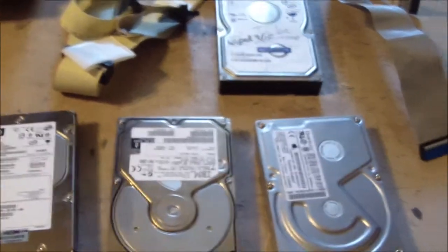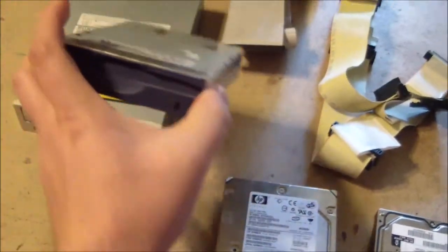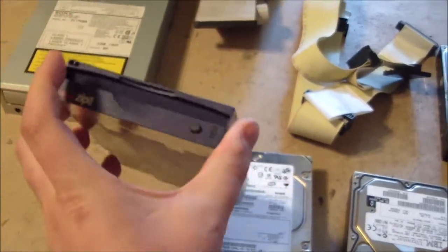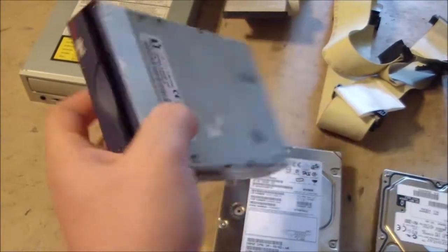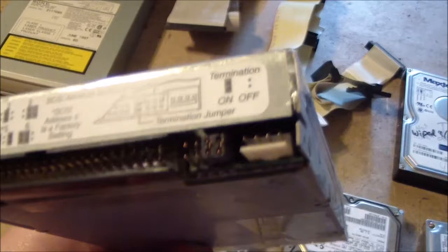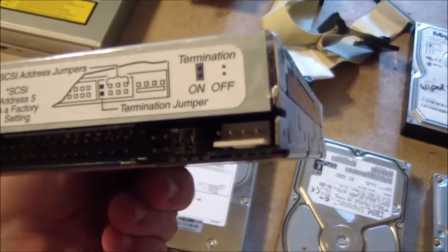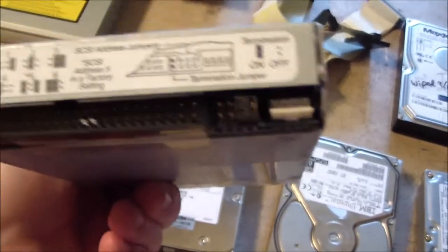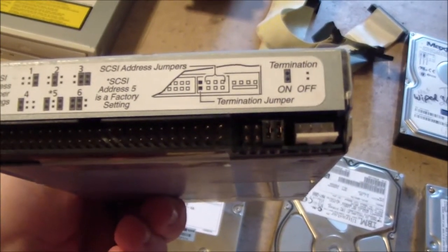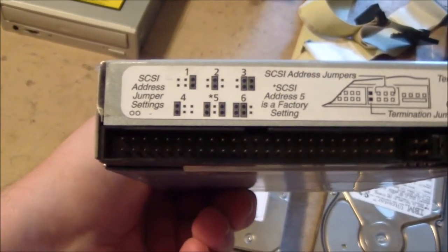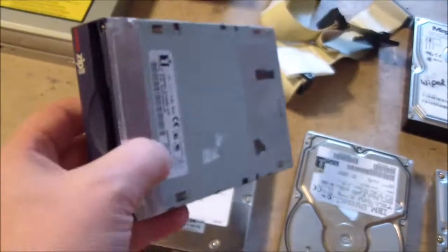And then lastly, I just have a couple SCSI devices. There's a lot of devices you can find in SCSI format, which is nice if you need more than, you're limited on how many IDE devices you can have. This is a SCSI Zip Drive, which I always found interesting because the SCSI versions used the floppy power connector, where the IDE ones used the 4-pin Molex. Again, you got your jumpers with terminators and whatnot, and it tells you what to do and how to set the device number and stuff.